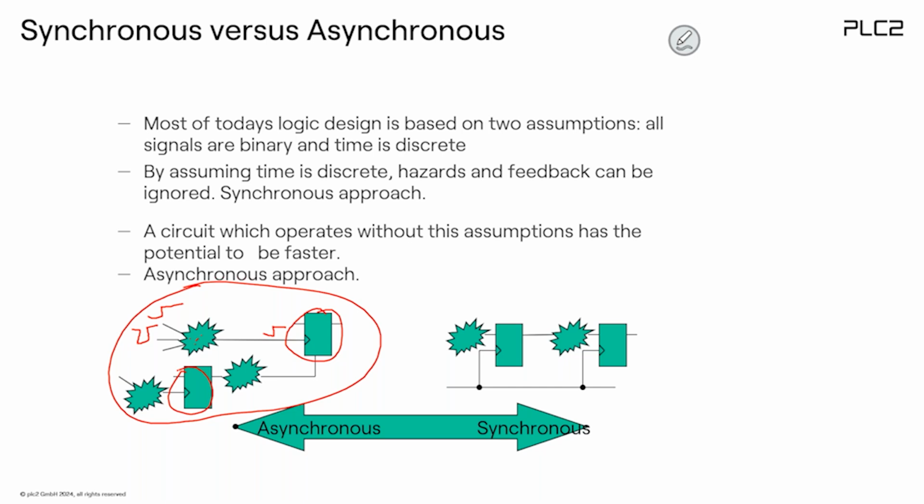Even better, you could take the output of a register like here, do some combinatorial logic, and use this to drive an asynchronous set or reset input. This is called an asynchronous approach. We don't have one synchronous clock in our design. The clocks are asynchronous, and the phase relationship of this clock is completely unknown versus that of this clock, even caused by some delay on the net.